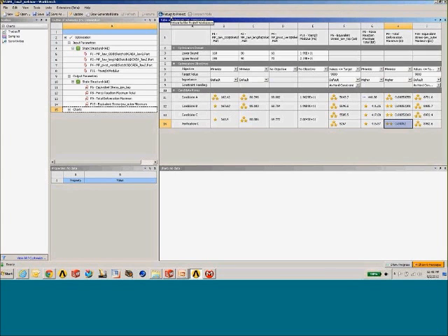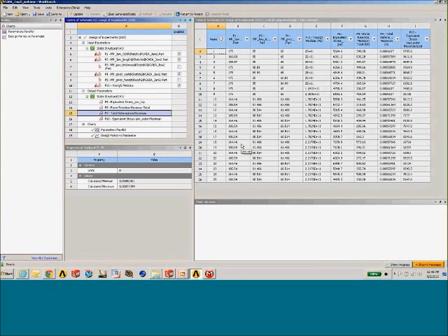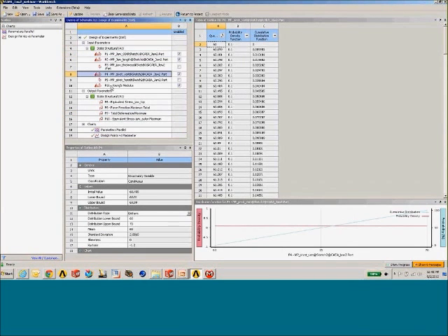One last thing to show you here. If we wanted to take a Six Sigma approach to the analysis, we could drag and drop that from the toolbar onto our project page. We open up the Design of Experiments tool. We're going to have a different set of design point variations here, because now we're assigning to the input quantities a distribution that is statistical in nature.